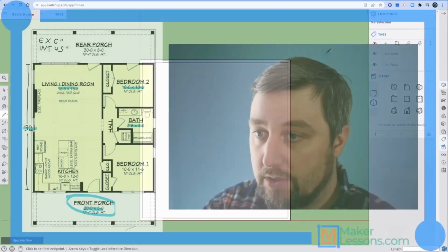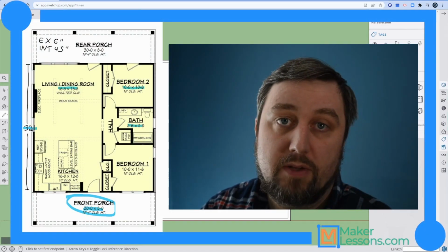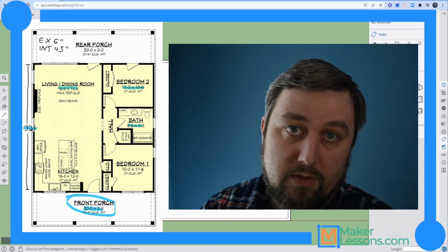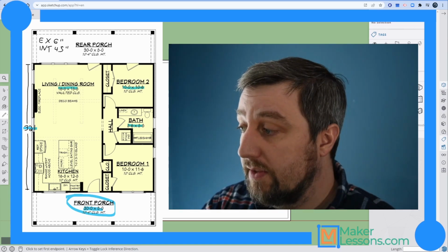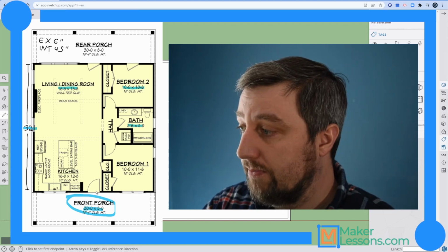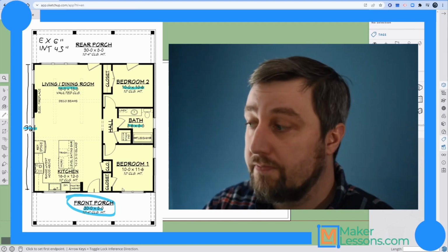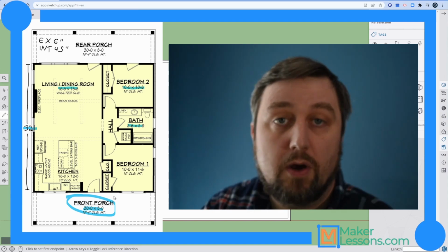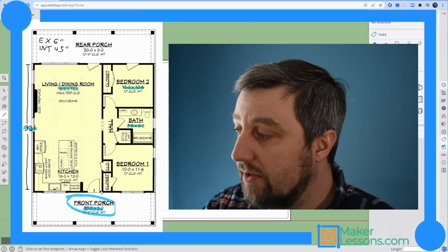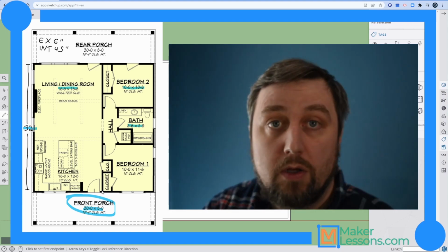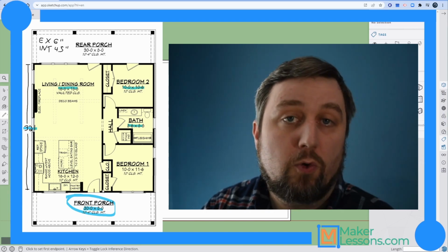The first thing we should look at here is, yes, they give us dimensions. No, they don't give us everything. So let's make some assumptions, right? That front door here is in the center of this front wall. Front doors, generally speaking, are 36 inches wide. And the door jamb, which is the space between the end of the door, or the hinges of the door, and a wall, more often than not is 4 inches, right?